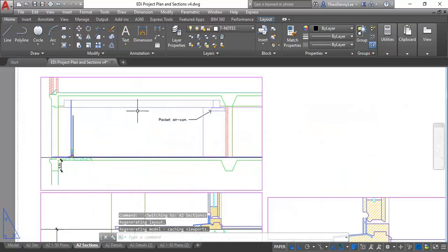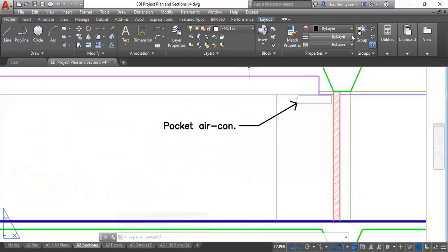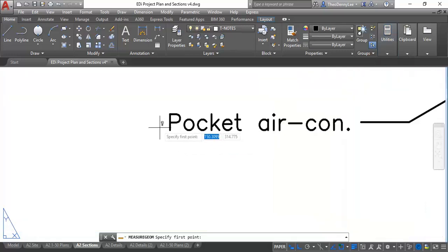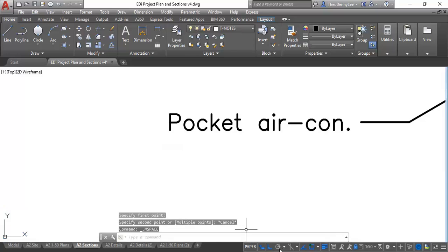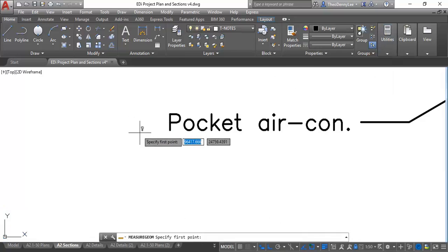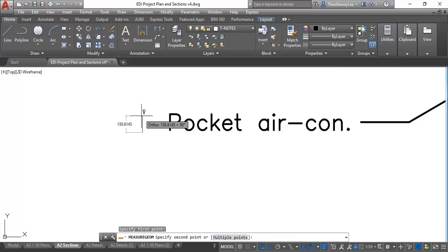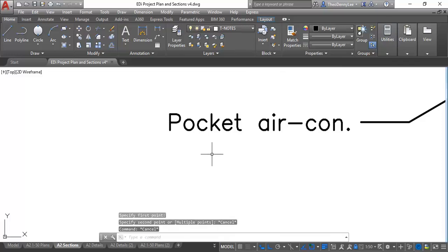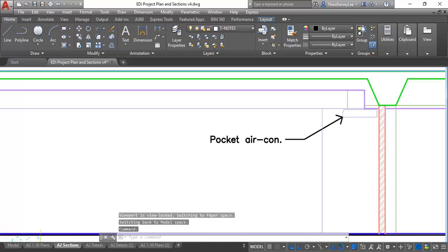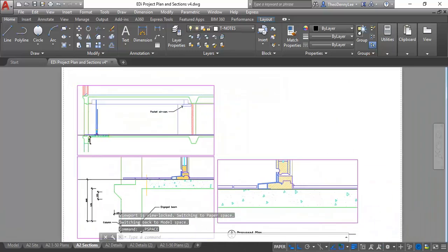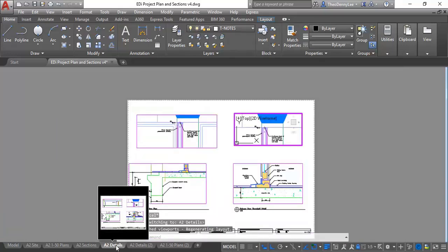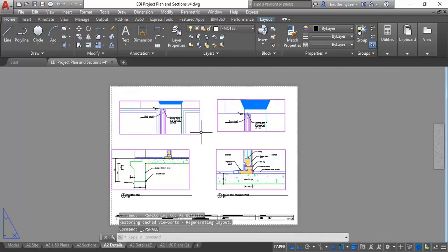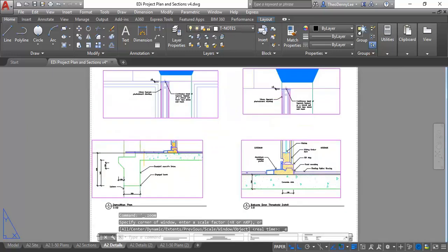A 1 to 50 viewport is probably a better example. So here, again on the page, in paper space, it's 2.5. But when I switch to model and measure again, 125. So regardless of what scale your drawings are, in paper space, dimensions are always the same size. Yeah, that's it. So again, that should be plenty for detailing. I know we've gone over time, but still that's good.